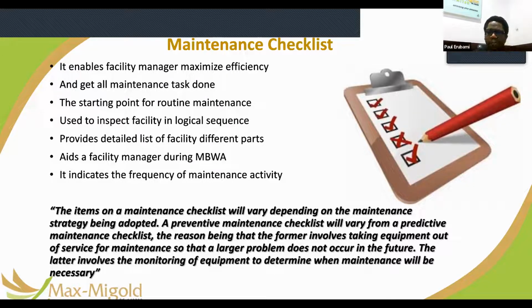By putting the steps down here, I have told the technician, I expect you to follow step one, step two, step three when you are doing this particular activity. So for every maintenance activity, I'll have one sheet. I can laminate it as a guide and put it all over the wall in the maintenance room. Whenever I'm giving you a work order to go and do a particular job, I give you that laminated sheet to say, this is the guideline for performing this particular task.